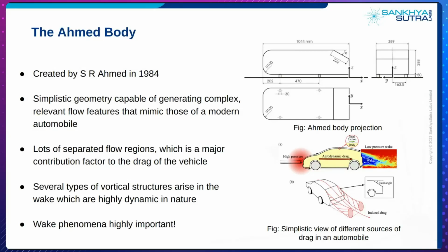And there are several complex vortical structures that arise in the wake of the vehicle, which is the rear end of the vehicle, which are highly dynamic in nature. They are quite complex in the sense that there's a lot of 3D interactions, which makes it highly challenging for the solver to accurately capture and predict. Another point I would like to reiterate is that the wake phenomena in any vehicle is probably the most important region that the simulation has to accurately predict in order to capture the macro features of the flow around the vehicle.